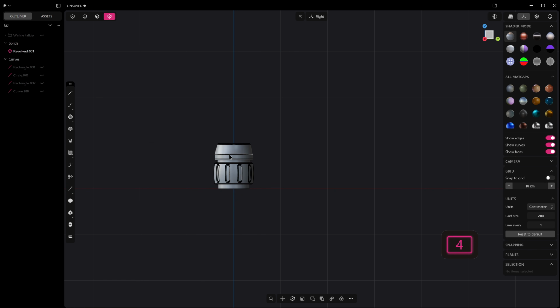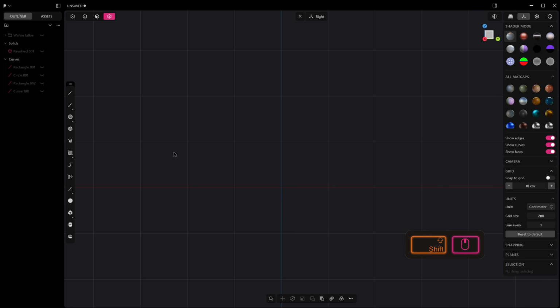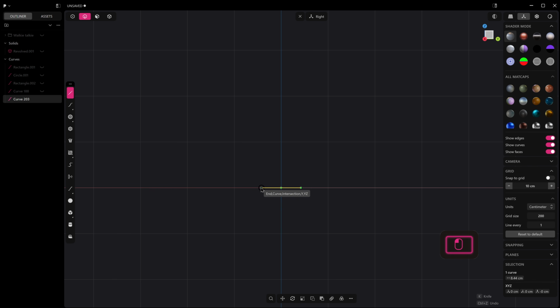Let's temporarily hide this object. Okay. And I'm just kind of spitballing now. We can bring out a line here. We can Alt X and we can mirror it across. We can press J to join those two together. Okay, I don't know if this is going to work.